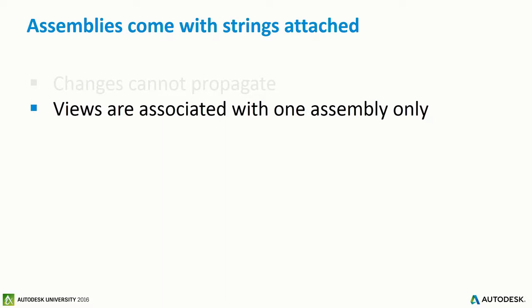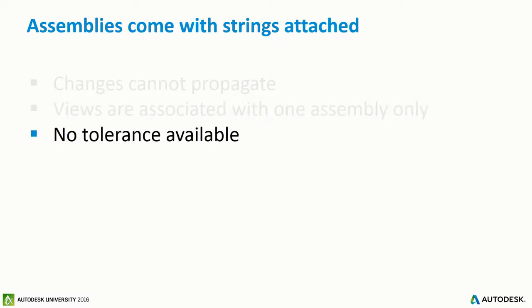Strings, right? These are challenges to utilizing assemblies for what we want to utilize them for. No tolerance. If that plate is 1/256th of an inch different than another instance's plate, they are not the same assembly. As far as Revit is concerned, it's really, really particular about this for some reason. But they wanted to guarantee geometric identicality. Just make up a word. So no tolerance is available.